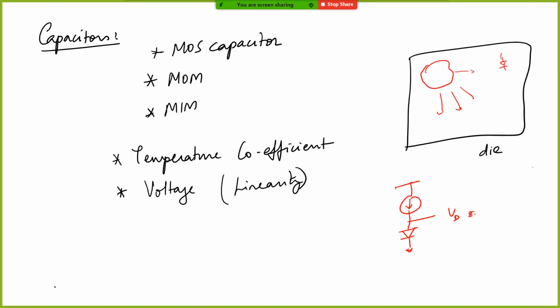All right. So that temperature is what is going to affect the value of the capacitance and value of the resistance, not necessarily merely the ambient temperature. The ambient temperature also comes into picture. And if you put it inside your laptop, the laptop itself will be heating up, right? So the ambient temperature there is different from what you would see in the room outside. So the actual temperature near the MOSFETs will be fairly high, even if your ambient temperature is low. All right.